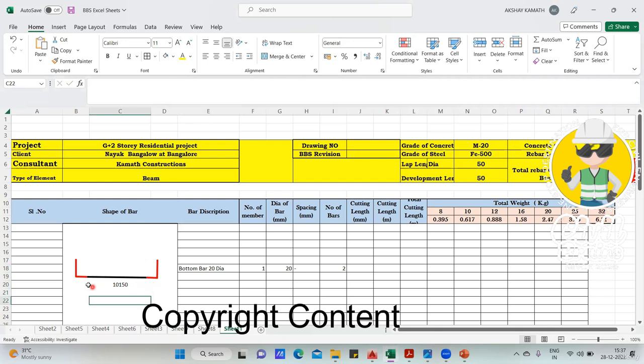Got it? Now this is your development length. That is the straight portion. Click here, write 460. This was 460. Then you select it and take it to the center. Or you can even keep it here. It's understood. Then again, come here, write plus 460, enter, it will go to the corner, select and bring it to the middle portion, bring it here. So is it understood?